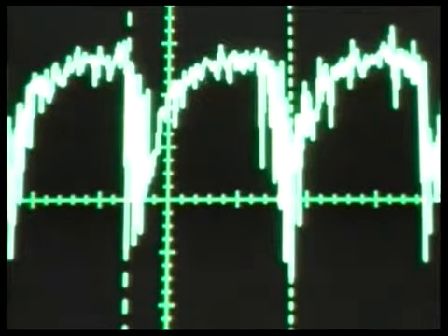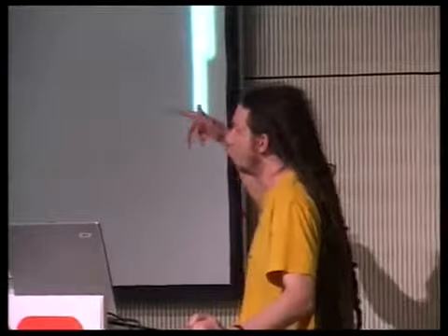Okay, so in this case, we're trying to find the instant in time at which a clock edge strikes. And here are some clock edges coming out of the VCC pin of the chip. If you remove the bypass capacitor, the chip still functions. But whenever a clock edge hits, that's when the chip is doing actual calculations, the voltage falls. There's not much that they can do about this because it's a power-efficient chip. You buy this because you want it to run on a battery until the end of time. And if they were to make it use this much power at all times, then you wouldn't get that advantage from the product.